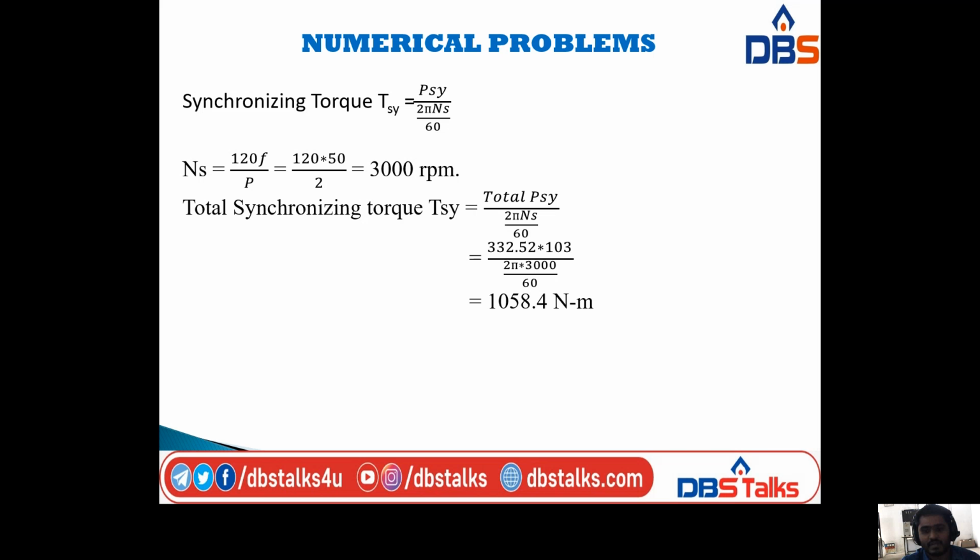So we know already the synchronizing torque, that is tau_sy is equal to P_sy divided by 2 pi Ns by 60. This 2 pi Ns by 60 is equal to omega, that is the angular frequency. So we already know P_sy, the synchronizing power value, and 2 pi by 60 is also known, but we have to determine the synchronous speed, that is Ns is equal to 120 f by P.